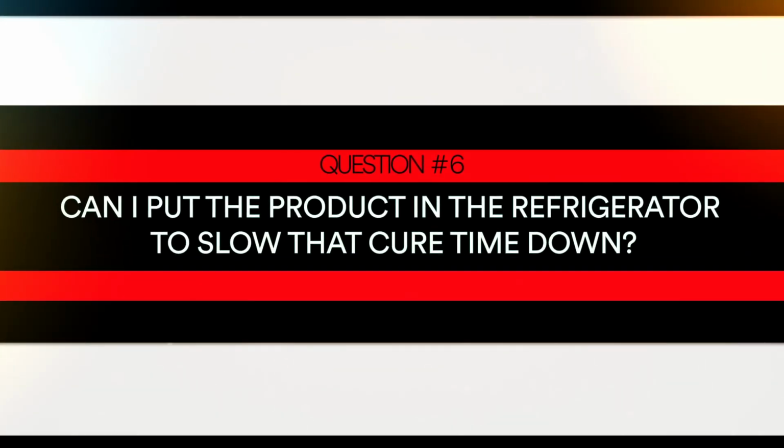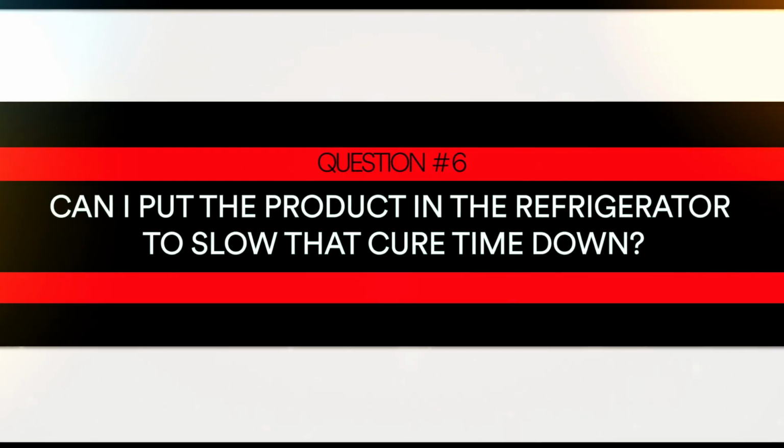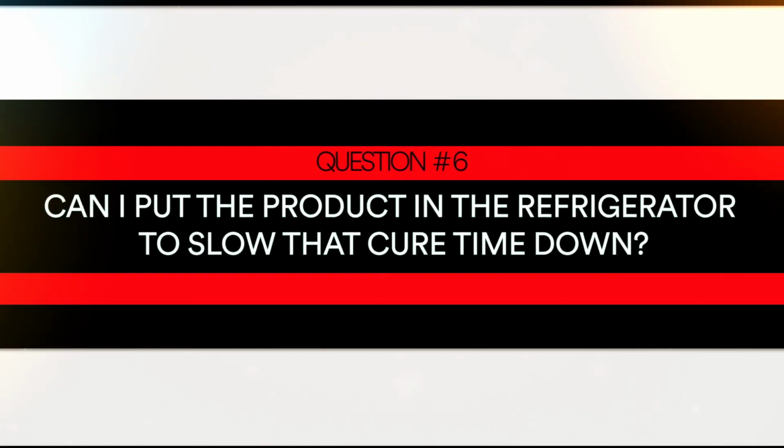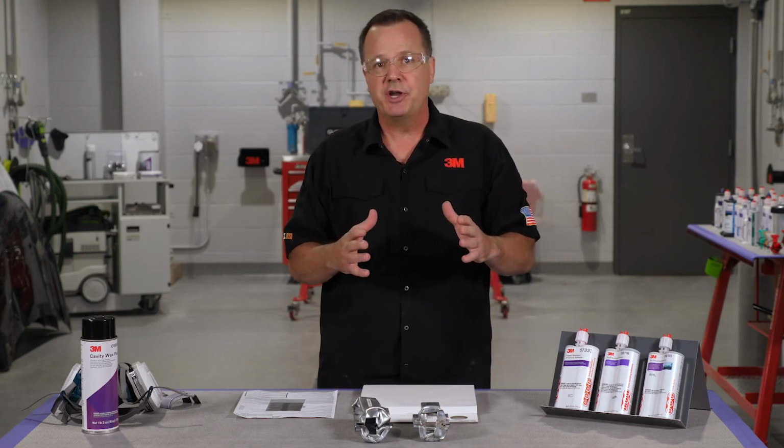Okay, so question number 6 is similar to question number 5, but the question is, can I put the product in the refrigerator to slow that cure time down? And the simple answer is yes. However, I would recommend maybe something a little less aggressive like an air-conditioned office rather than a refrigerator. But as long as you're monitoring how cold it gets, you absolutely don't want it to freeze, but just cooling that product down will give you a little more cure time.